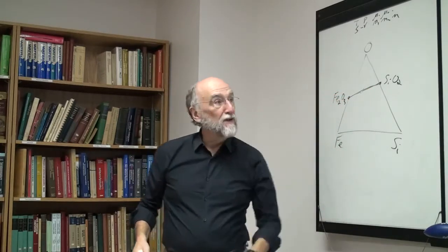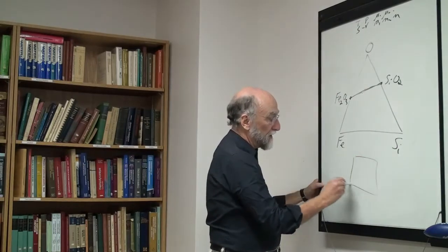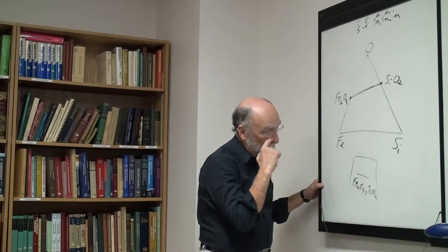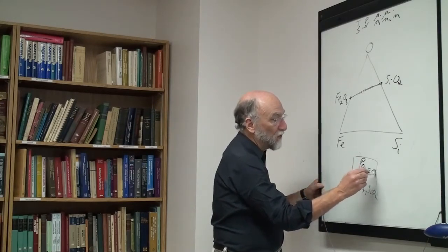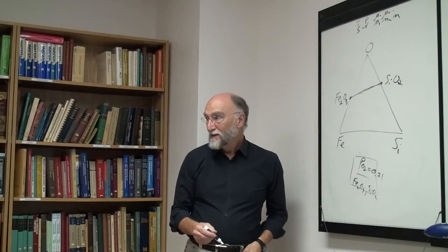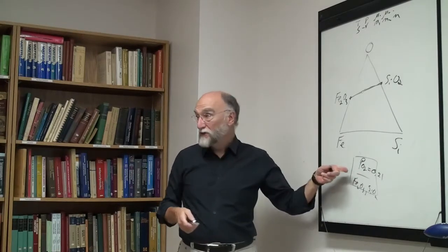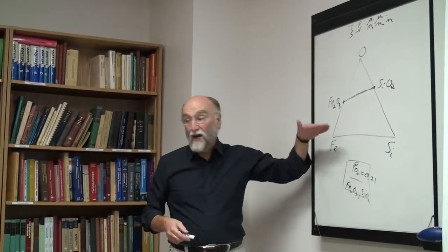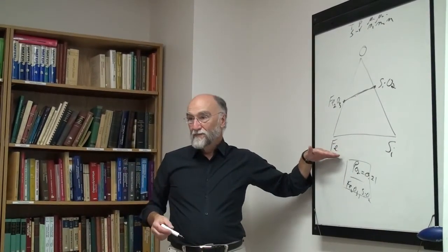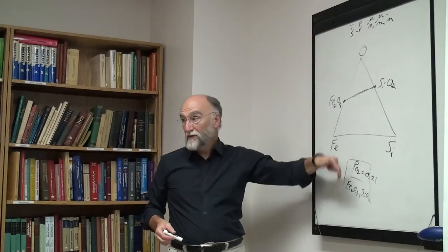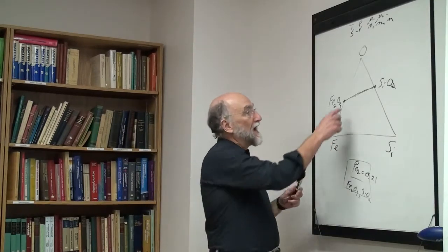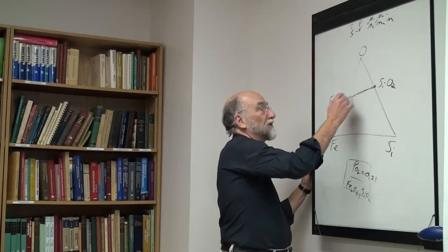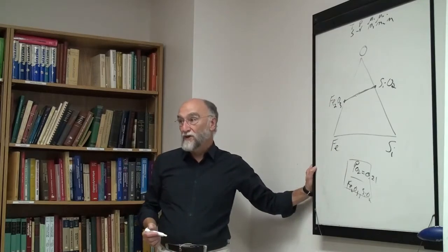Okay, what I'm doing now is I'm not doing that. I'm starting off with Fe2O3 and SiO2, say at 25 degrees. I'm fixing an oxygen pressure of 0.21. Okay, and now I'm heating the thing up, so I'm keeping the oxygen pressure constant. This is very different because now I'm imposing an oxygen pressure on it. So the oxygen could go in or out of the phase when the thing reaches equilibrium. And now I am not going across this line. What I'm going across is a line of constant PO2.